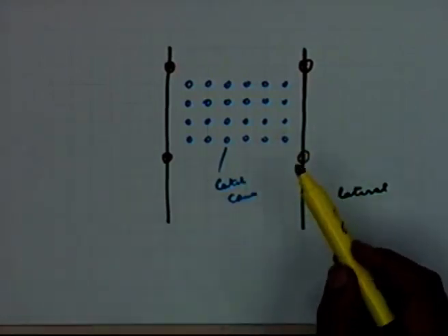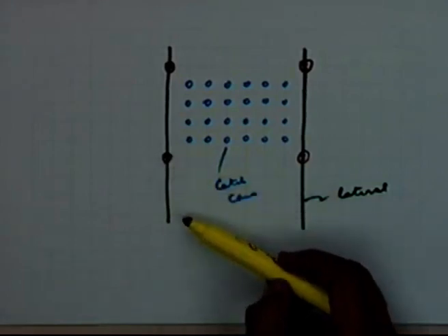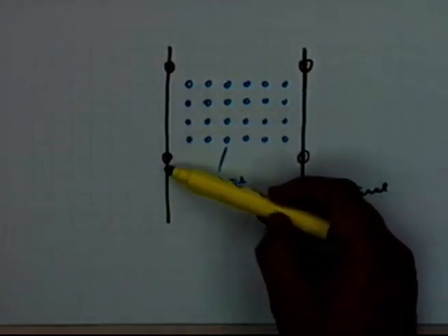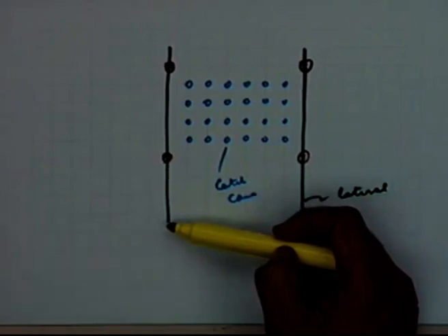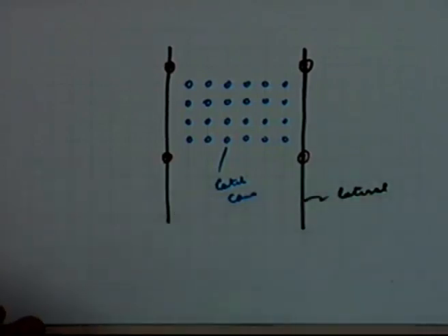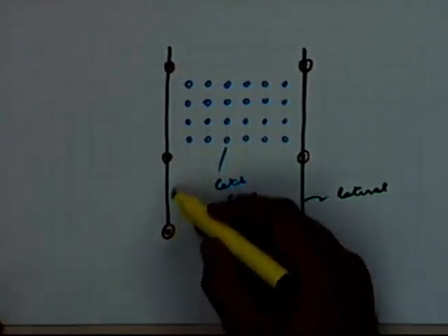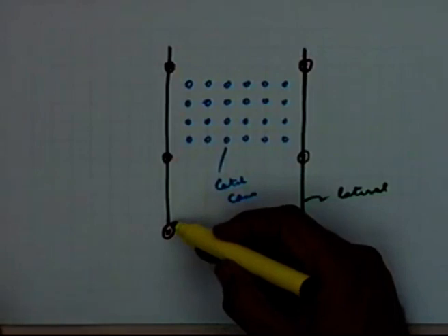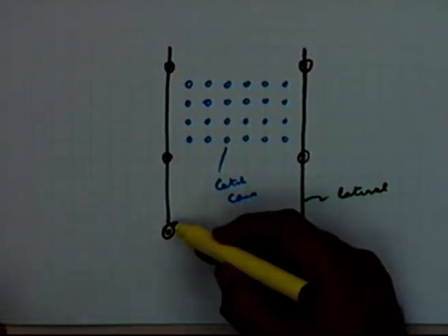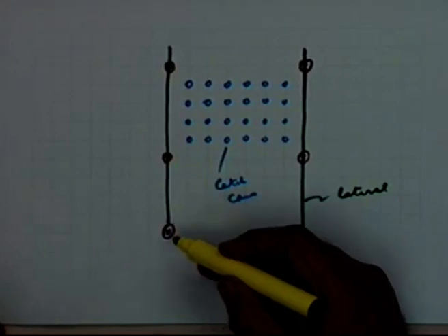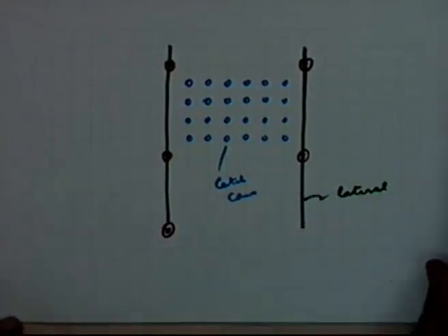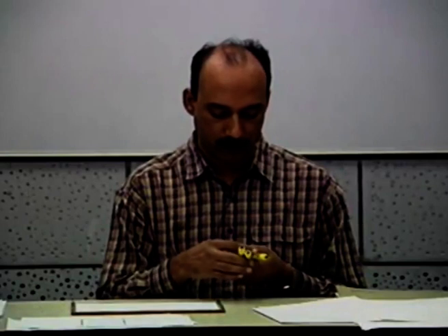Whereas it depends on the situation. If your spacing is such that the overlap is such that even a sprinkler head which is somewhere here, at the next location, is also influencing this area, then you will have to take that also into account. So it's entirely dependent on how your system is designed, and the uniformity coefficient has to be obtained accordingly.